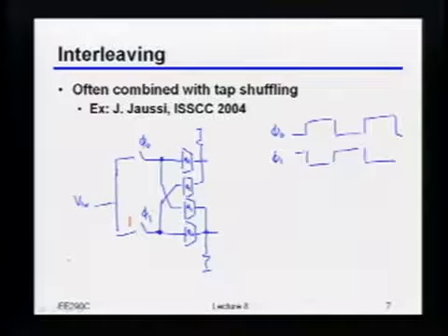Yeah. So why are these architectures being developed on the receiver end? Okay. So there are multiple different reasons. In the high-speed link context, as I mentioned, it generally is not used that often. But there are other contexts where it makes a lot more sense. To give you an example, I can't always talk to my own transmitter, right? So if I need some sort of feed-forward equalization, which I'm going to need if I have any significant precursors in my channel, then my only choice really is to build it on the receiver, right? Because if I can't tell my transmitter to do it, then I'm stuck. I just have to do it at the receiver, right?